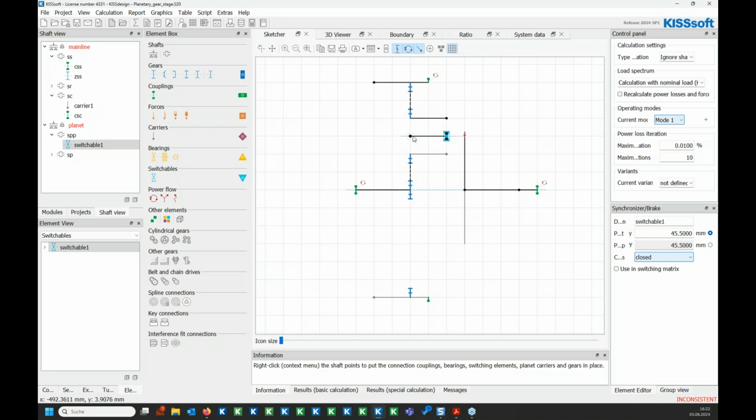So relatively, the pin has no speed, so we have to set the speed of the pin to 0, and the gear body will automatically have the relative speed in the shaft calculation, and this will give us the correct bearing lifetime calculation. So it's a different handling than in KISSes. This is important to know: kinematics will work only if the pin shaft is set stationary.